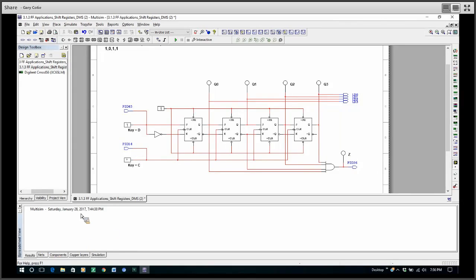And if you go looking back up through the error message, it's something about a clock phase signal, but it has to be a PIO 14. There are other clock pins, and if you need them, we can always give you that information. So let's take a look at this.